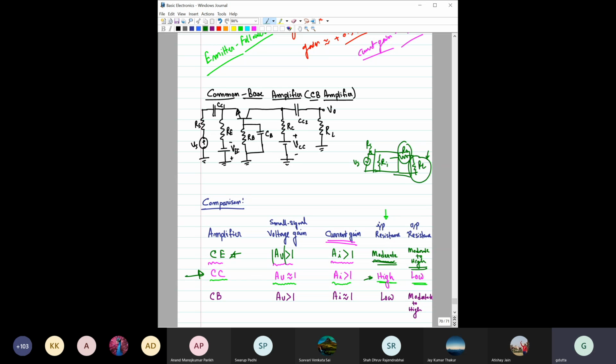In most cases, not only one type of amplifier is used, but different amplifiers are used in series, because in some cases matching impedances is very important, and in some portions of the amplifier the gain is the most important thing, right? We are not going into much more detail, but remember that when designing any practical amplifier, it is not only one type, either CE or CC amplifier. It is a cascade of two or maybe even three different types of amplifier.